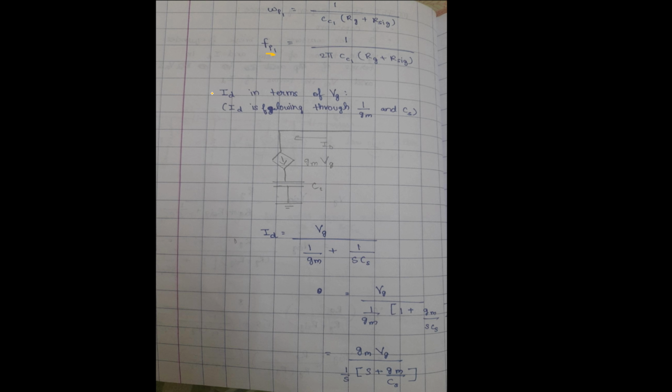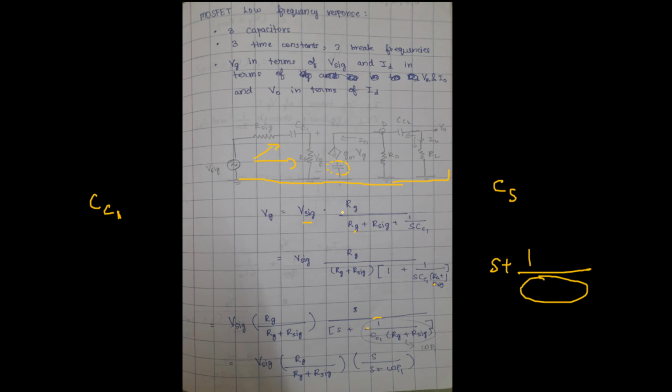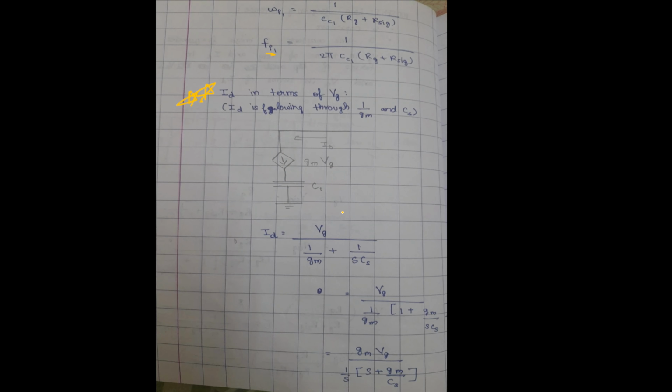Right. Now this is the different part, because this is quite different to the emitter capacitance that we spoke about in BJT. The other two capacitances, CC1 and CC2, are almost the same, so there is nothing different about them. So now let's see how this works. We open circuit all the other capacitances and we just look at this.